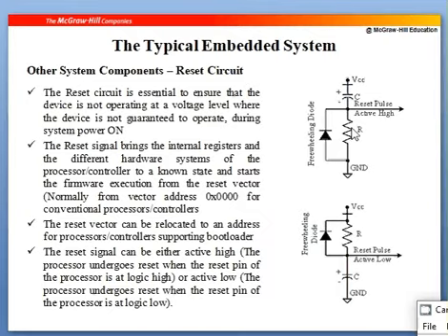So slowly it will decay, depends on the RC value, but initially from low you get a high signal. Slowly it goes towards 0, low. So that's what happens, hence you call it an active high, because for a short duration you get an active high signal. That is the discharged voltage which will be obtained here at these terminals.